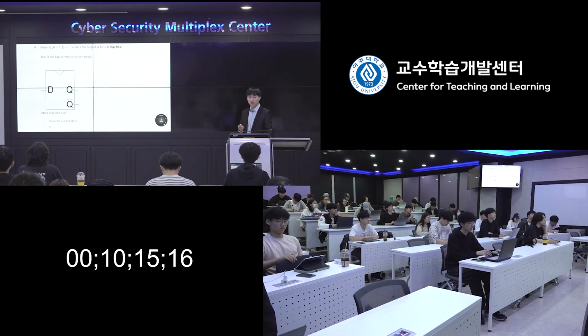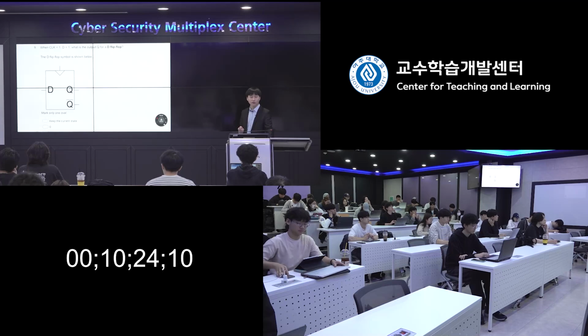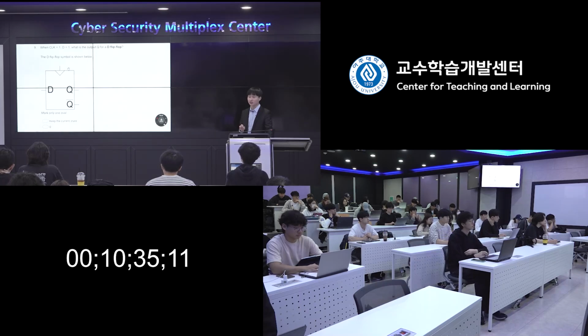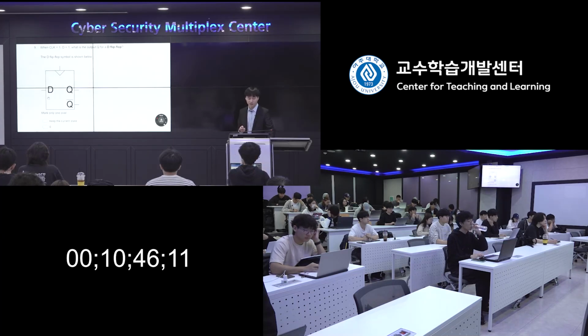So you see here the symbol of the D flip-flop. The clock input has a triangle. The triangle indicates that the Q, the output, will only be changed or switched at the rising edge or falling edge. So you can consider that this triangle is like a falling edge or rising edge. Whenever you see this kind of triangle for the clock, it means that the output will only be updated when there's a falling edge or rising edge.